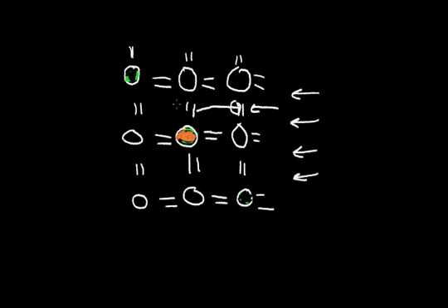It has an extra electron that's just sitting there. Now if we apply an E field, this electron can move. So if we add more phosphorus atoms, we add another electron that's free to move around. So we can change the conductivity. Instead of an insulator, we can make this a conductor by adding more phosphorus atoms.